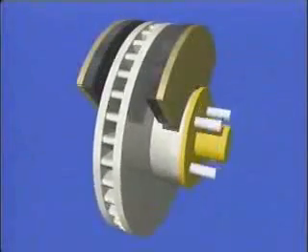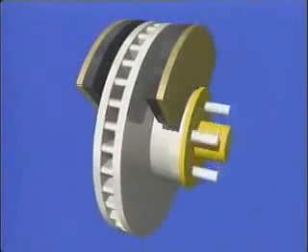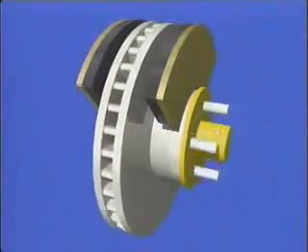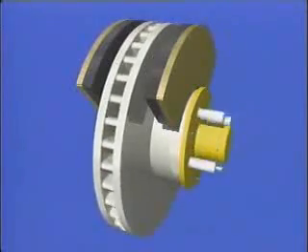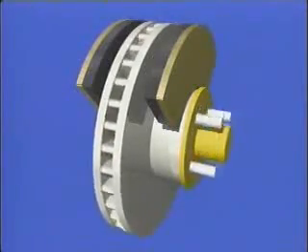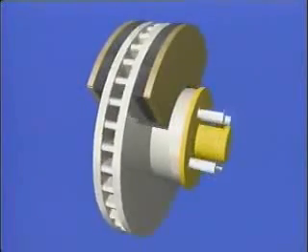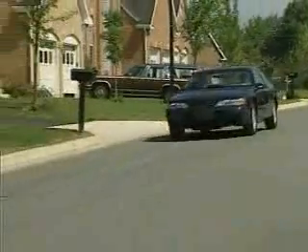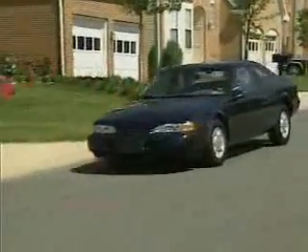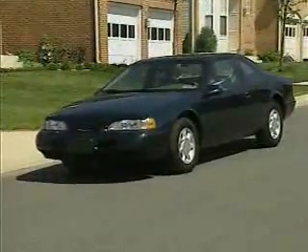Different levels of lubrication are possible. One level is no lubrication. When there's absolutely no lubricant between moving surfaces, the surfaces are dry. This condition causes the maximum friction between moving surfaces and should be avoided as much as possible, except for applications such as braking, in which maximum friction is desired.